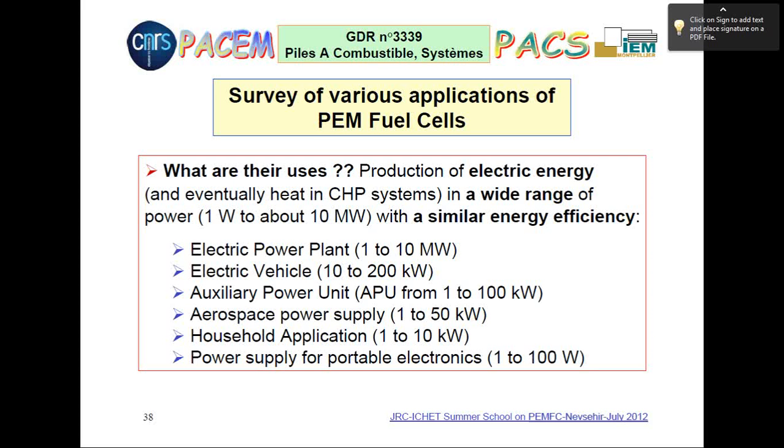Yes, we can discuss. You have given various examples on the membrane, electrode, and so on. What about the interface between the membrane and the electrode, and what role is played here? Because we were discussing in the morning the use of liquid Nafion to seal or to bring close contact between the membrane and the electrode. How can we play with that?